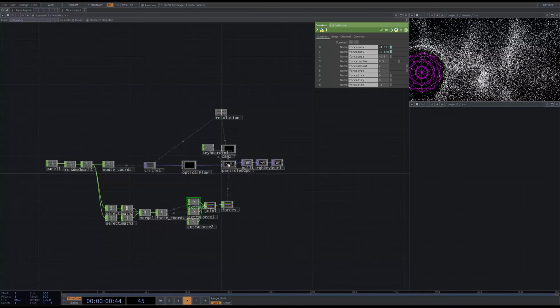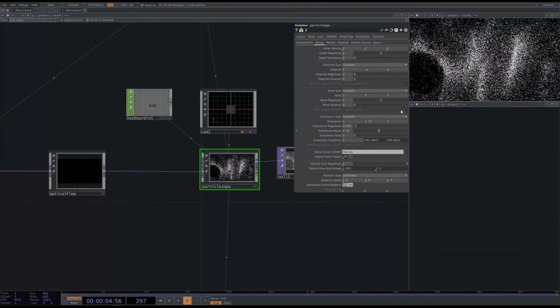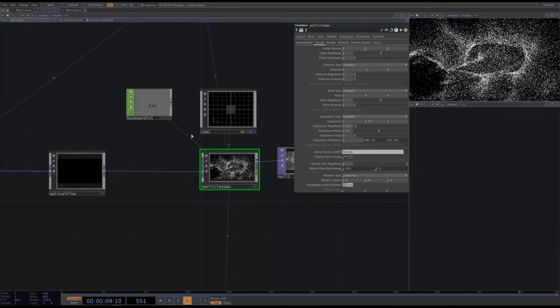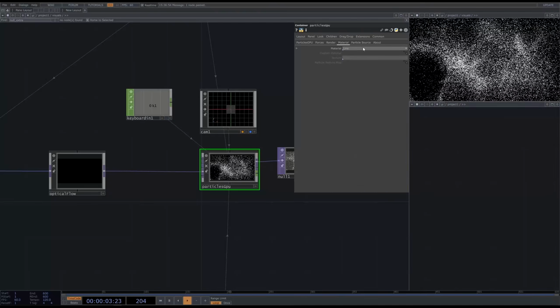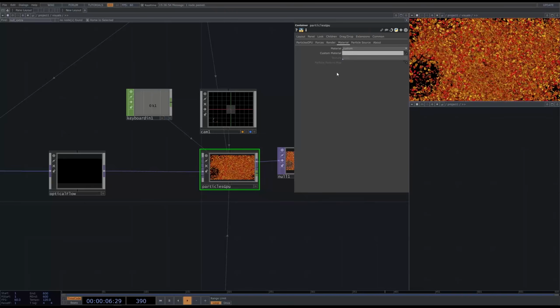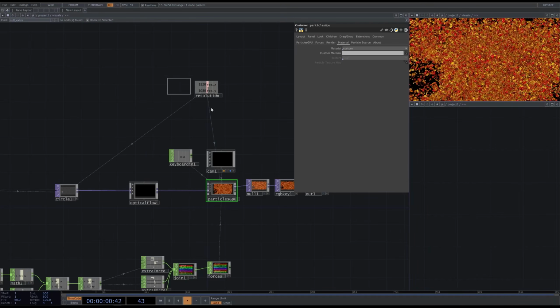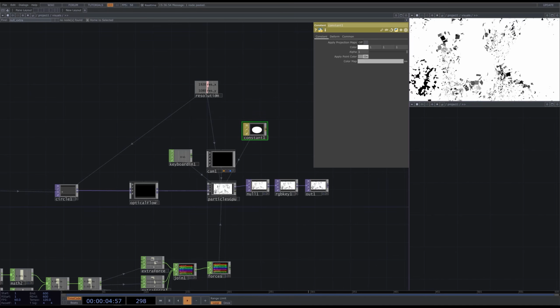Okay, now I can disable this forces wireframe. Let's go to the Material tab and choose the Custom Material. Create a constant material and reference it by dragging onto the particle component and choosing Custom Material option.